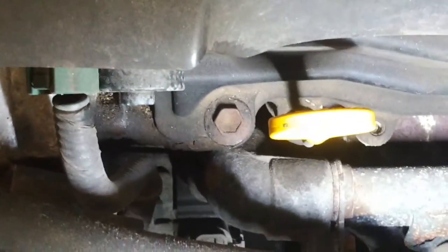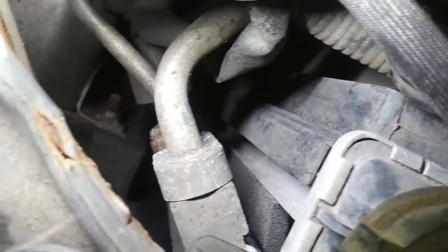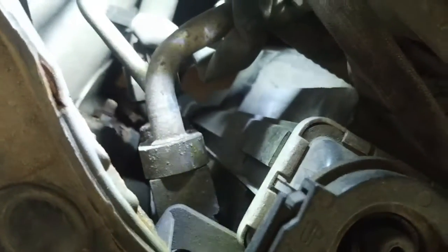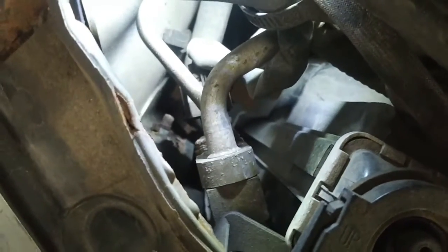The lines here. No, I don't see anything obvious. So there it is, right below that condenser block. You can see just below the high and low pressure lines on the condenser, there is a threaded-in pressure sensor. Man, that's not easy to get to. Well, we're going to shut it off and have a look at the connections at least.